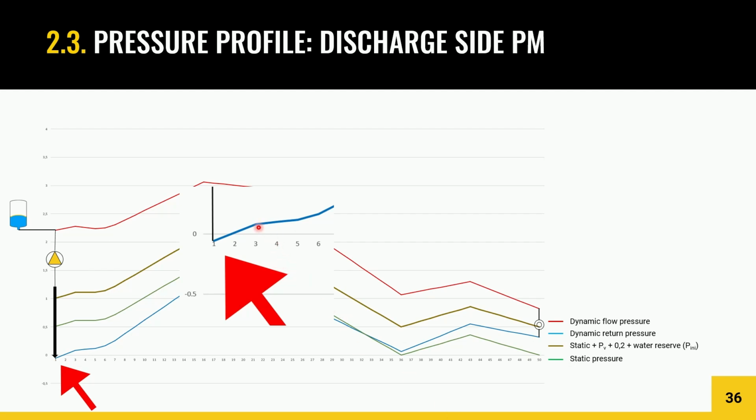And these conditions can be seen in this screenshot. So you can see the pressure has dropped below zero, which means air is being drawn in. Air ingress harms water quality. So if you put oxygen into your system, you'll get corrosion, which reduces efficiency and increases maintenance costs and energy consumption.